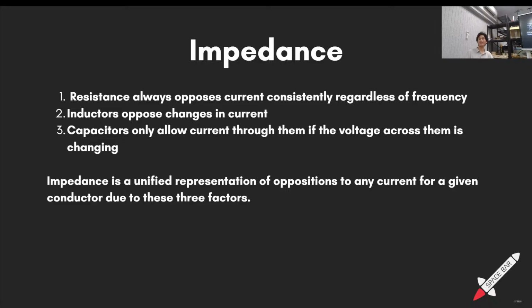Yeah. And depending on what circumstance you are in, a few or all of the components will matter. So this thing in the impedance is just making it not perfect. Yes, absolutely. Okay, any questions about this? We're not moving on until everyone is happy because this is really important. So capacitor resists voltage change, inductor resists current change, going from an ideal wire to non-ideal.